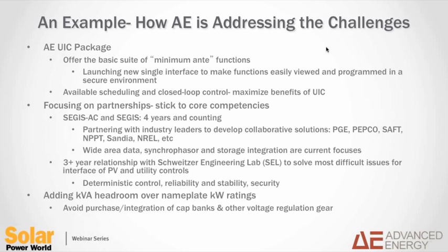And just to give some examples: volt-var control, looking at the frequency on the grid and controlling your active power output, looking at voltage on the grid and controlling your active power output. So there's a number of focuses in that R&D effort. We also have a relationship with Schweitzer to help us solve some of the issues around closed loop control at kind of a plant level.